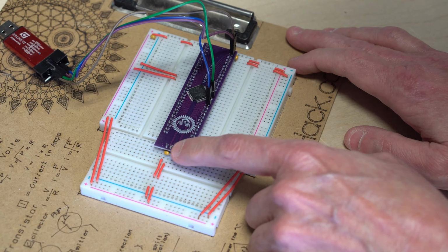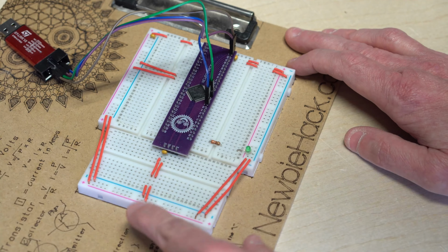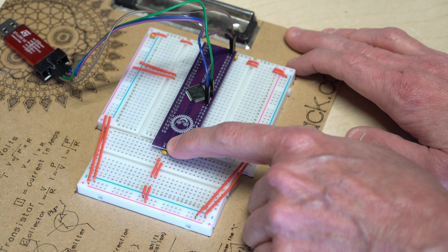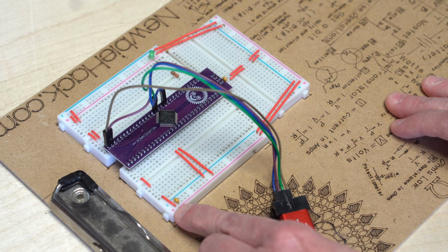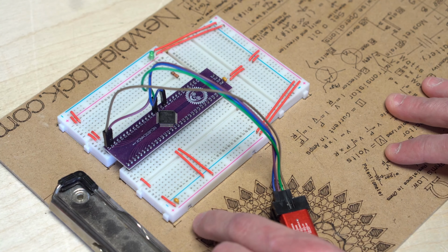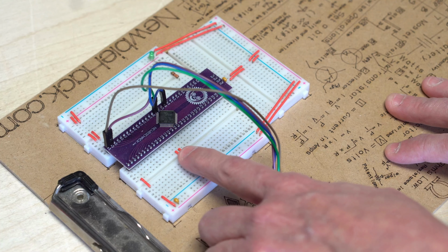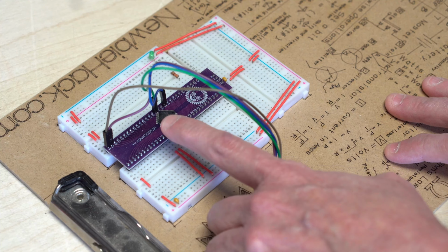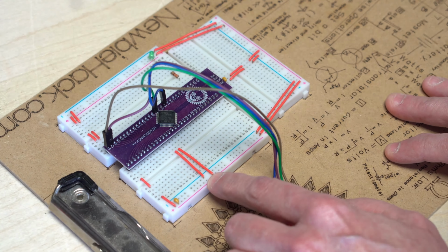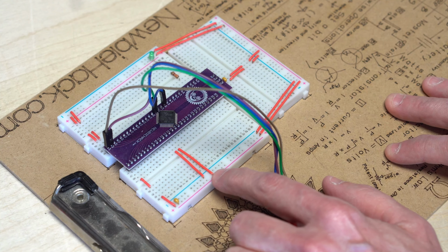Pins number 31 and 32 are also power pins, and pin number 32 is connected to the positive, and pin number 31 is connected to the negative. Pin number 1 is also a power pin, and it's connected to the positive. Because the PLL clock uses the VSSA and VDDA to power its clock, pins number 12 and 13 need to be connected to the power as well. Pin number 12 is connected to the negative, and pin number 13 is connected to the positive.